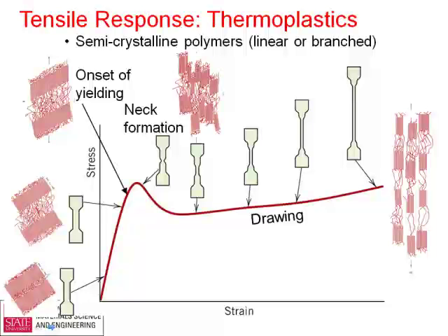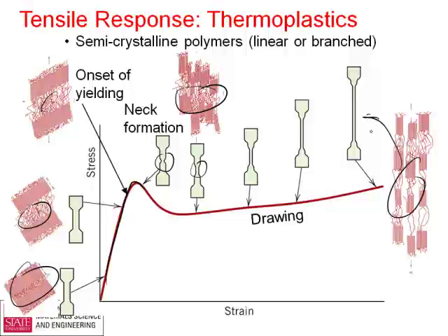So in terms of tensile response, again, you can see this as a structure that changes properties. If you start with a fairly crystalline polymer, these can be kind of disoriented. Here's the amorphous regions, and as you go through, you see a peak in the load. You can form a neck, and this neck elongates, and these necked regions are areas where the material is very highly aligned, and where the material is very highly aligned, you actually see improved properties because your covalent bonds are all lined up in the tensile direction.